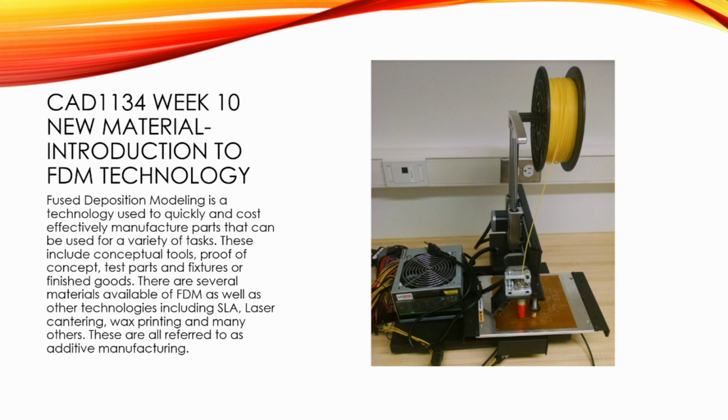It's become so cost effective now to do laser sintering of metals that we're seeing production parts for medium volume things. I know of a camping stove with a little insert where the only way to cost effectively manufacture this little part is to laser sinter it. That's a fantastic little piece of technology.